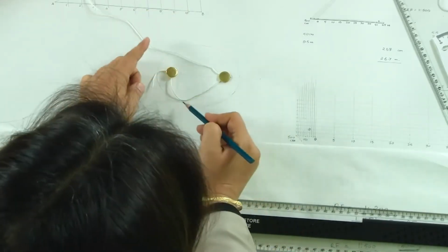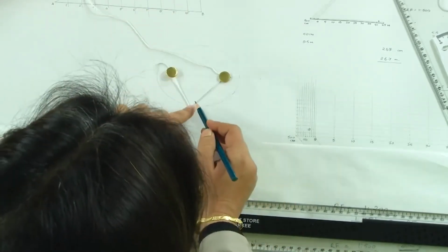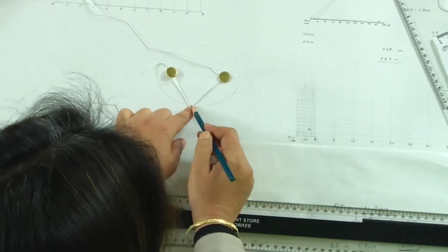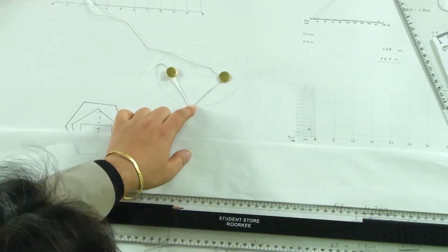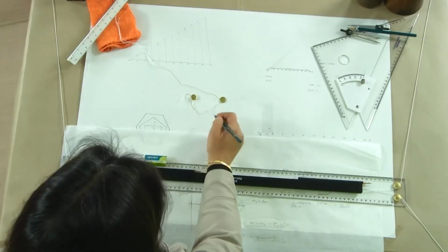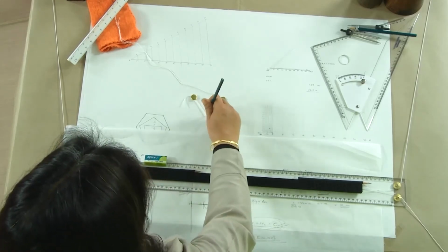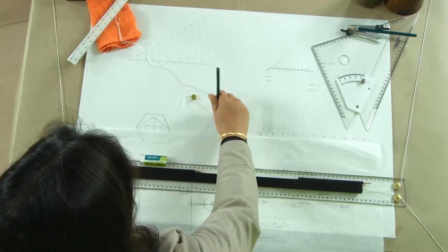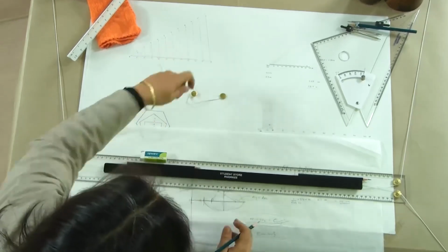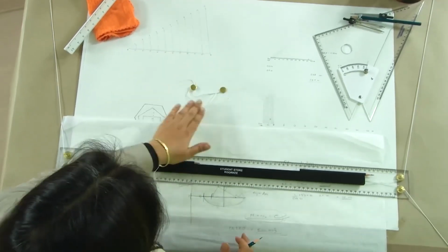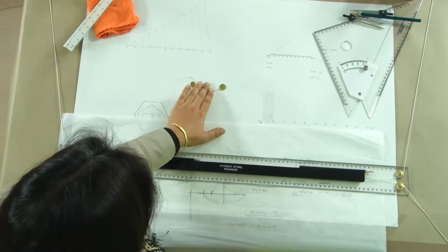thread, the length of this thread between the 2 points has a sum total of this distance, which we know as this constant. So, we know the distance between the two focal points, we know the total constant, which is the distance of a point from these two, and we simply trace this path. This is our ellipse, and you can see that we get a very firm regular ellipse with this method.